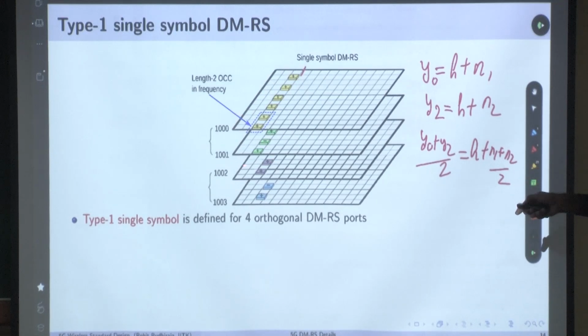But you look at this, these sequences are defined over the same subcarriers and they are orthogonal. So these two ports are orthogonal in the code domain, because you are making them orthogonal using this length 2 orthogonal code cover. Now differentiate these two ports from those ports. What is happening here? How are they orthogonal? They are orthogonal because you are using different resource elements, that is, orthogonal in frequency, not in code. You do not need an orthogonal code cover to make these ports orthogonal with respect to those, because they are already orthogonal in frequency, right.